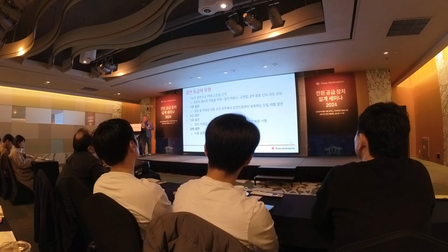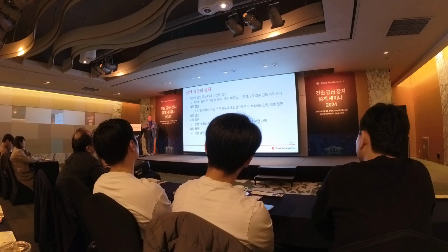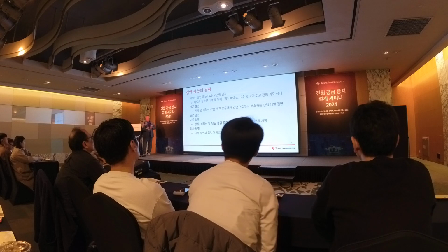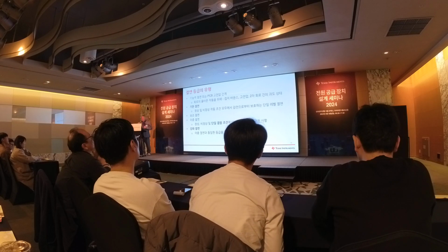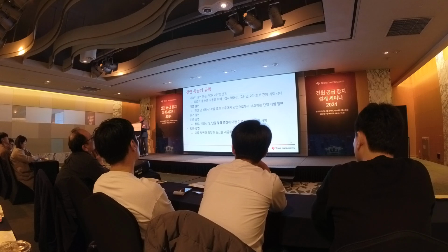So maybe we have a high voltage gate drive circuit in which we need to isolate it from the low side gate drive. The spacing that we use, the creepage and clearance that we use, is only related to proper operation of the circuit. It's not related to safety, it's not related to any other parameter other than just the circuit functioning properly.